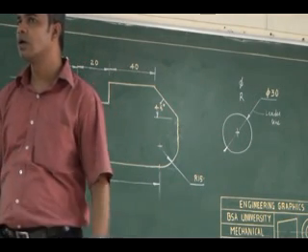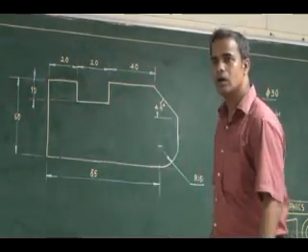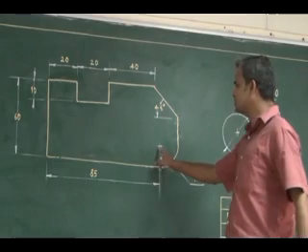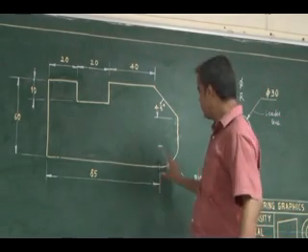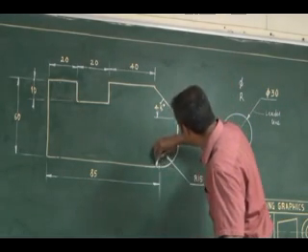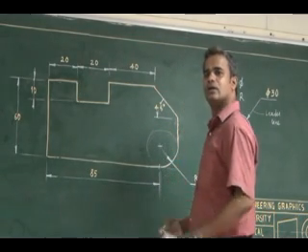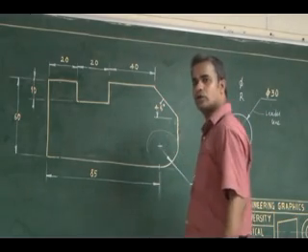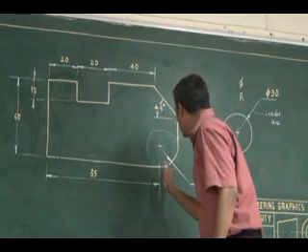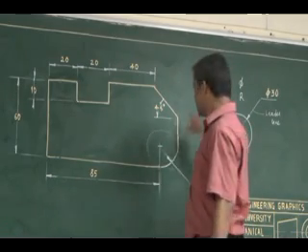How to draw the arc? Which arc? Sir, the arc is 15 mm long, sir. So how to draw it on the object? Compass. Measure 15 mm in your compass. You mark the center here. This is 85, you know. From here, this distance, what is the distance? It is 50. So it is nothing but a circle of radius 50. As per our convenience, we can choose the exact center, not any center. From this location I can go through the center. What will be the distance? 50. From there, I can draw an arc.